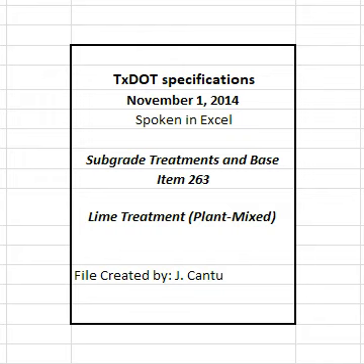Complete placing, compacting, and finishing within 72 hours after the lime is added to the base material. Start lime operations only when the air temperature is at least 35 degrees Fahrenheit and rising or is at least 40 degrees Fahrenheit. The temperature will be taken in the shade and away from artificial heat. Suspend operations when the engineer determines that weather conditions are unsuitable.